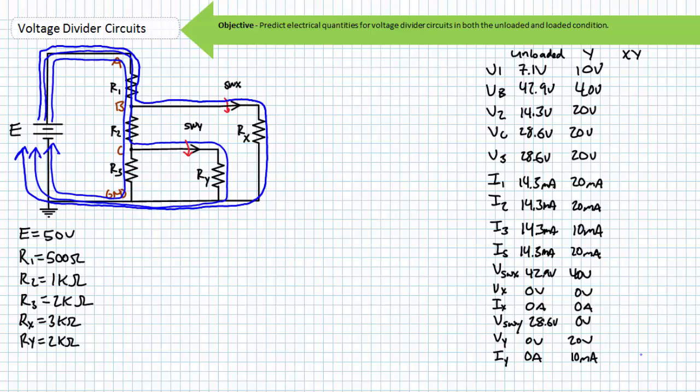The current bound for load resistor Rx travels through R1 before getting off at node B. The current bound for load resistor Ry travels through both R1 and R2 before getting off at node C. In this case, source current increased because the addition of yet another path in parallel decreased total resistance seen by the source. As can be expected, everything will change.